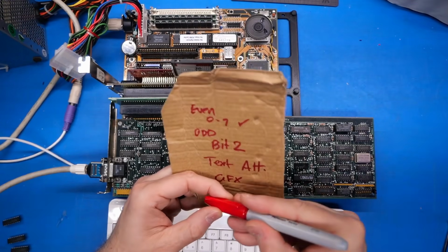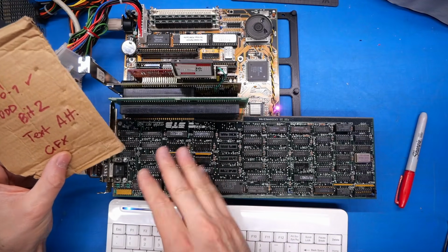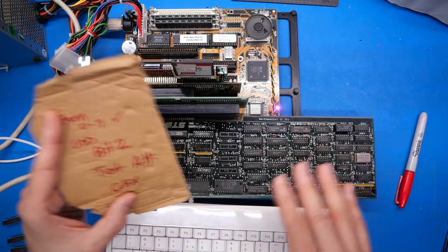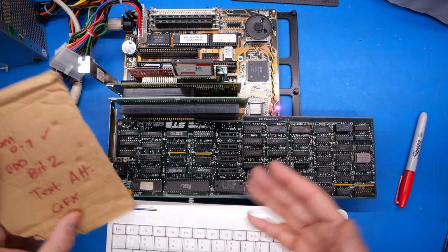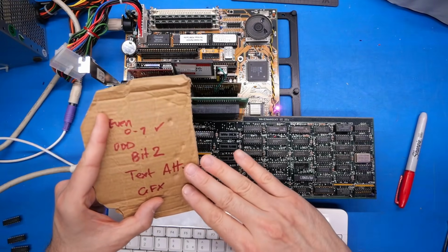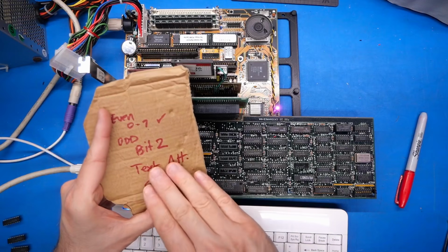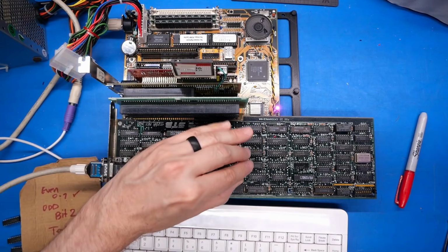And the thing is, I'm pretty positive that the circuitry that generates the pixel-based graphics on a CGA card is separate than the text and the attribute color stuff. And it gets mixed together at the end and selected depending on which mode you're displaying. So the problem exists between the RAM and the graphics circuitry that generates both of these modes. So in other words, I think the problem is very close to the memory itself.